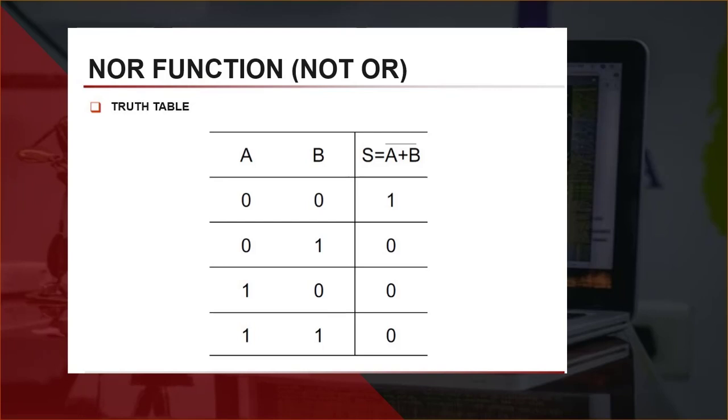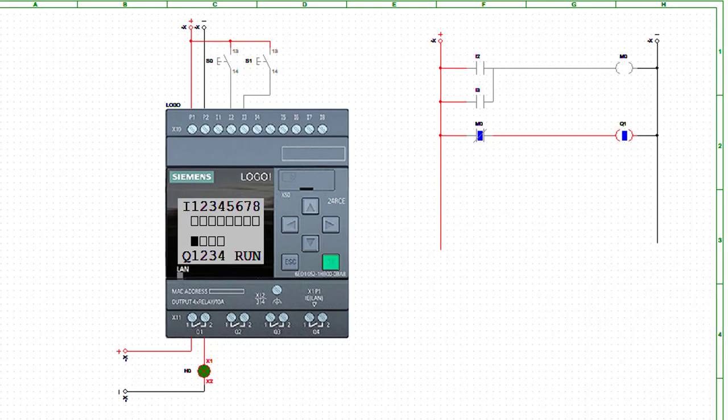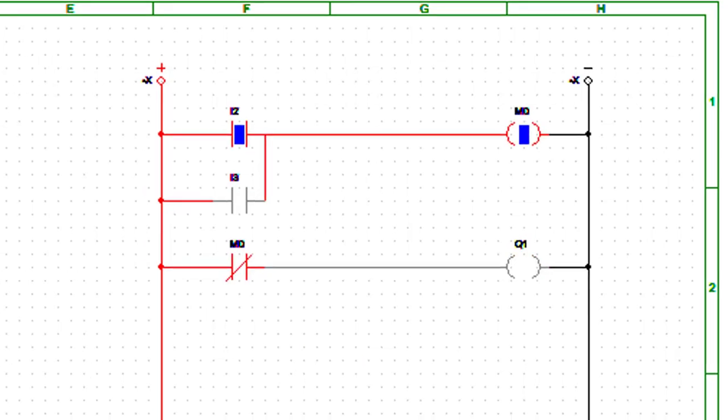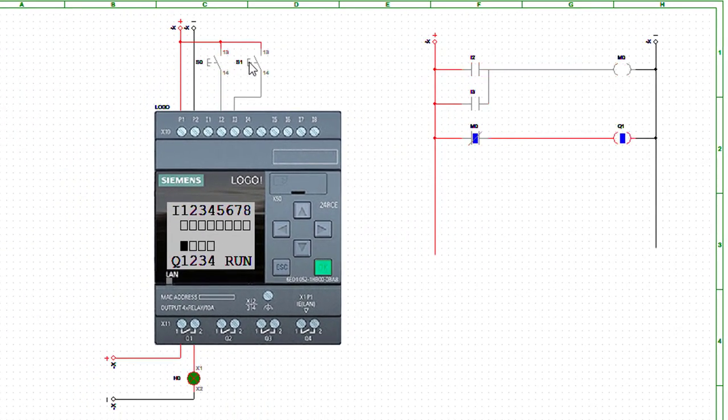Observe the behavior of the NOR function. Basically we have a Boolean sum, inverting the result. See the example in the PLC below. Note that we have the PLC connection the same as the previous example, but now the ladder programming corresponds to the NOR function. We have two inputs in parallel, and the auxiliary memory, being responsible for inverting the result of the combination.